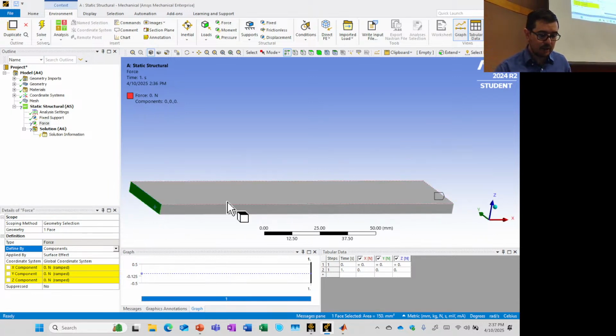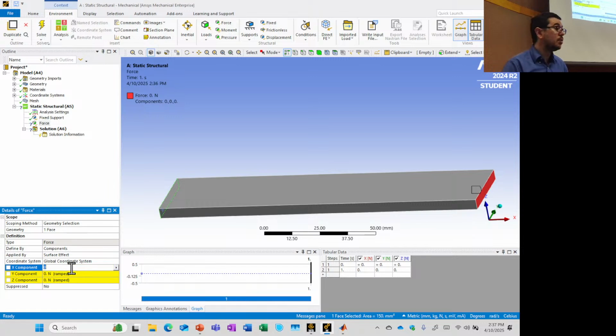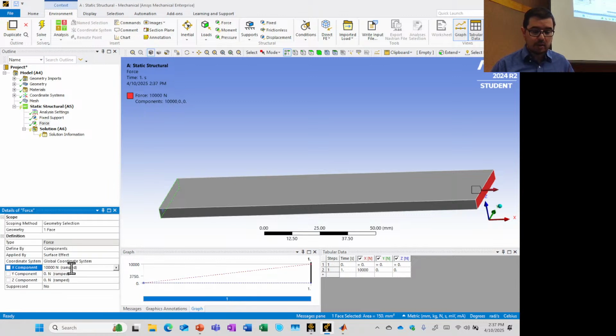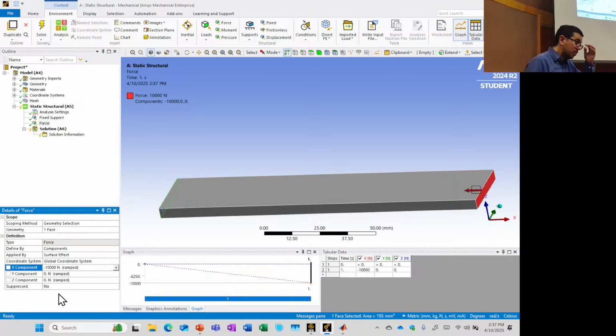This is compressed, okay, and then over here, actually, I haven't specified the minus x yet. So now I'll put, and we said it was 10,000. That's quite a bit, 10,000 newtons, right? That's not an insignificant load. So 10 e to the 3. If I just do that, though, that's going to be positive, right? So instead, I need to do negative, like this, because I'm interested in buckling.